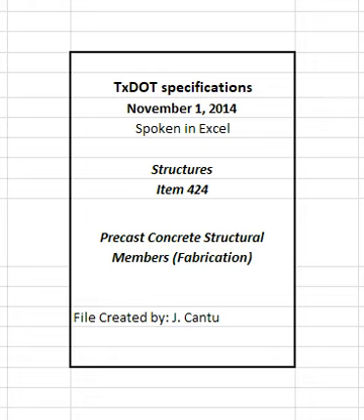4.2.5.3.1 Internal vibration. Insert vibrators into the concrete immediately after concrete placement at points spaced to ensure uniform vibration of the entire concrete mass. Limit the insertion spacing to within the radius where the vibrators are visibly effective. Allow the vibrators to sink into the concrete by their own weight and penetrate into previously placed lifts that are still in a plastic state to thoroughly consolidate the layers together and prevent cold joints.